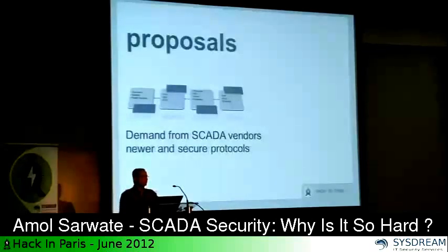Make sure that your SCADA vendor gives you newer protocols, as we saw in case of DNP3 and Modbus. There are newer secure protocols available, so make sure that your software has those, and also make sure that your administrators are using those protocols. So it's not just that your software supports secure DNP3, but it also has to be enabled.